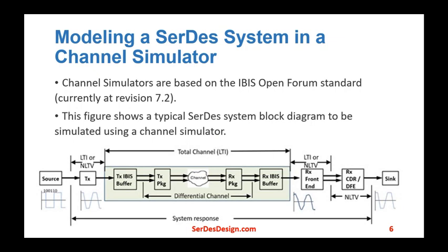Modeling a SerDes system in a channel simulator. Channel simulators are based on the IBIS Open Forum standard, currently at version 7.2. This figure shows a typical SerDes system block diagram to be simulated using a channel simulator. This block diagram is generic for any channel simulator, but each tool has its specific way to represent this block diagram. The constituent parts of this SerDes system include the following: the transmit IBIS-AMI portions.